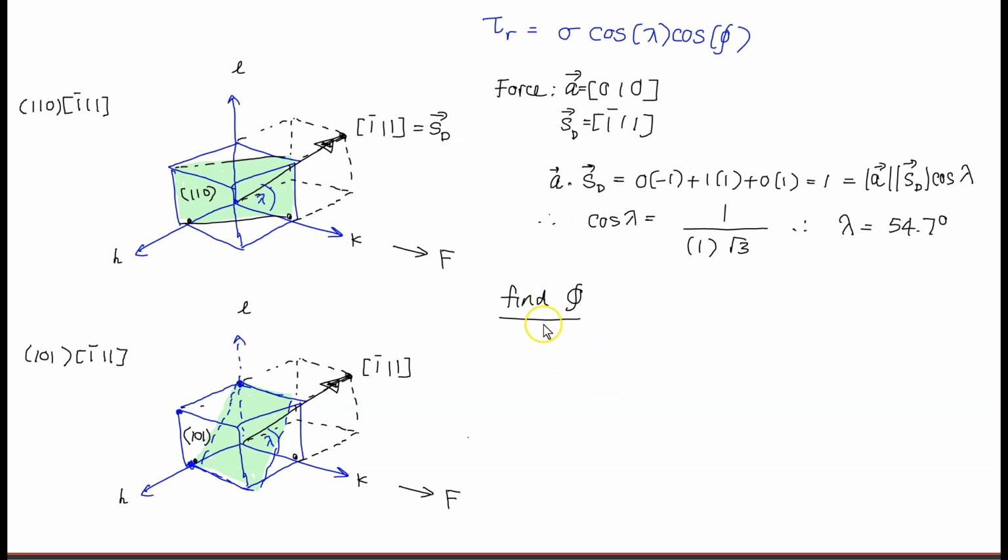So we can say that here the direction 110, dot that with the F direction. This is equal to the size of this vector, which is root 2, again, I'm just using dot products, times 1 times the cosine of phi 1.